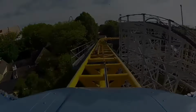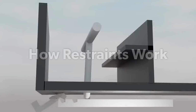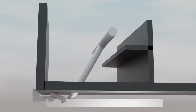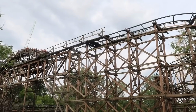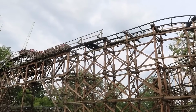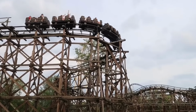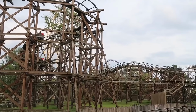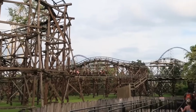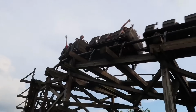The oldest and most simple restraint type, the latching restraint. These restraints can only be set in two positions, opened and closed. They use a spring-loaded bar under the train or ride unit to latch the restraining device, usually a lap bar, in place. To change from open to closed, these restraints usually use a foot pedal that an operator must physically press. Due to this restraint system's design, it has no preference between being opened or closed, meaning that these restraints can come open during a ride cycle relatively easily when compared to the others we'll talk about in a moment.